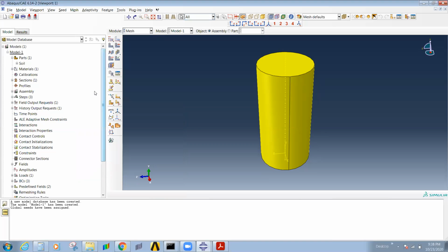I'll show that. So mesh: a very fine mesh. It is not small, it is too fine. I was thinking to take 0.005 instead of 0.01. No, even if you take that, your solving time itself will increase.